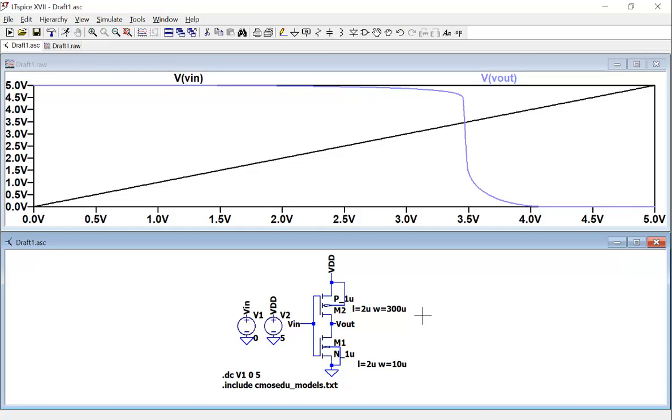So you know that by changing the width of the transistors, you can make that transistor more powerful, by giving more current through the channel to the output. If you want to make a strong transistor to reduce the time delay or to drive a big capacitor, you should increase the width to make a bigger pipe on the top. Just think about this transistor as a pipe. Increase the diameter of the pipe so you have more water flowing down. So that's the concept here.